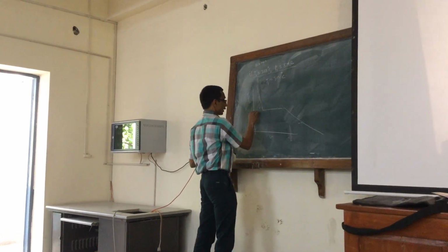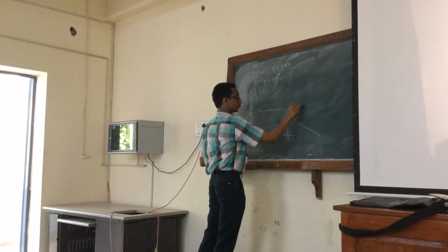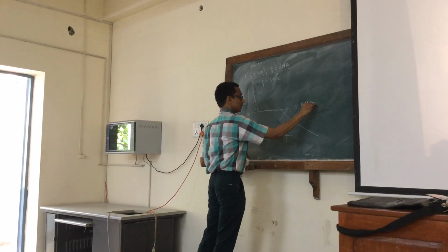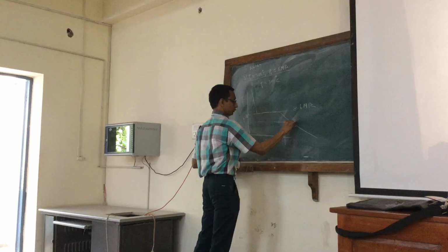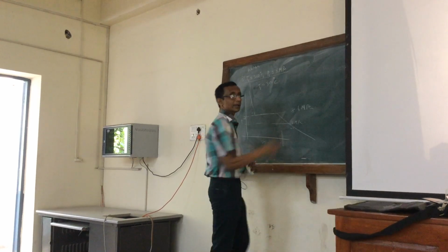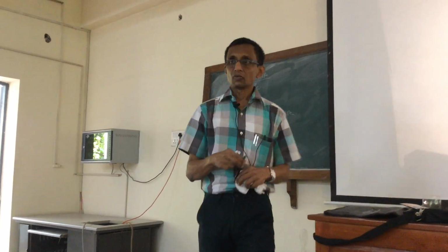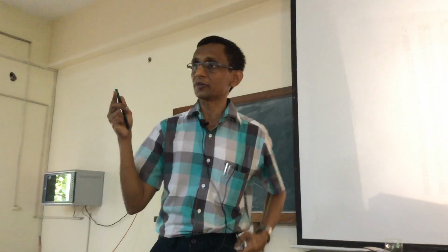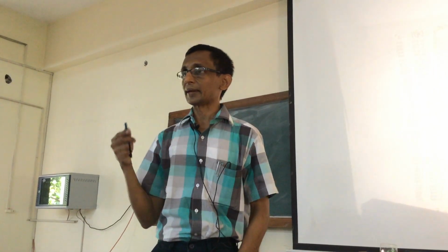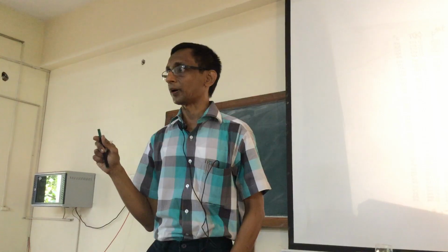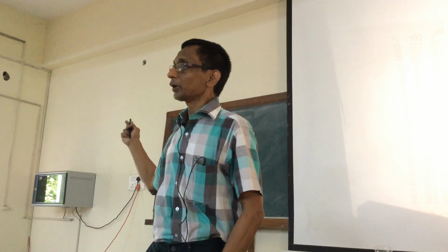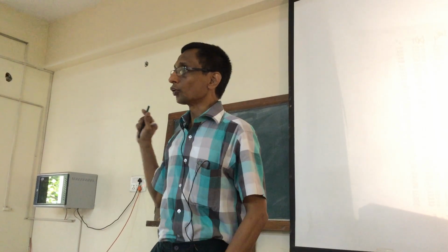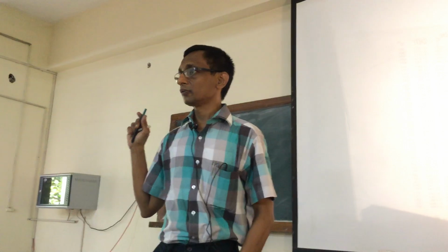So I can now mark this. This is 8.6 megapascal. So clearly 8 megapascal is somewhere here. Now we have verified that this is superheated, because in the terminology of the tables, rather than saying it's gas, you have to call it a superheated vapor. Because now you have to go to the superheated vapor table to calculate the fugacity.